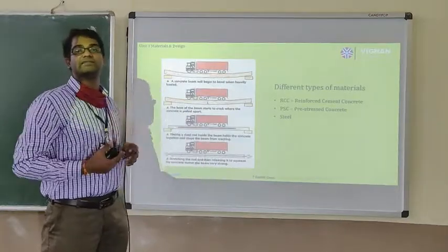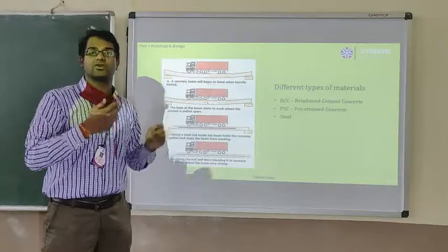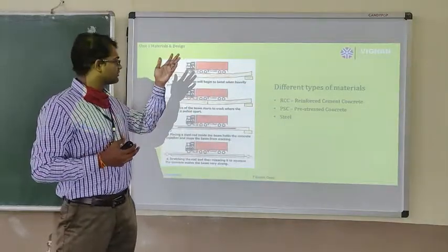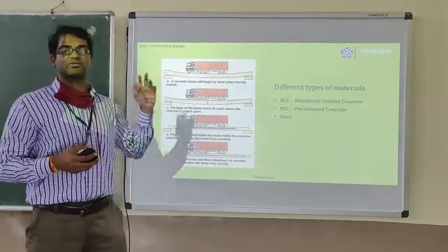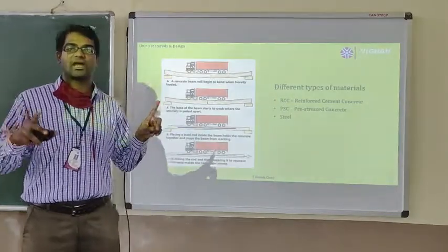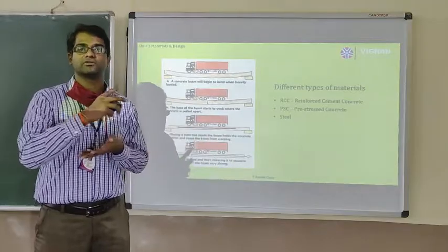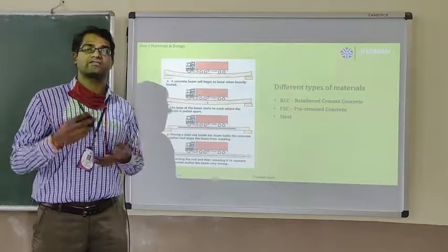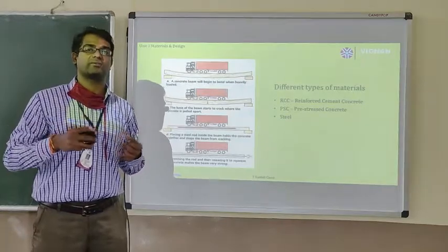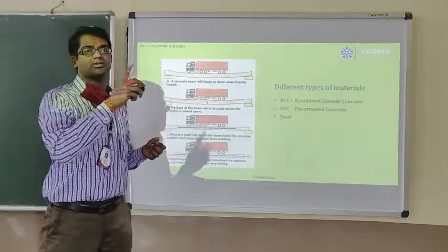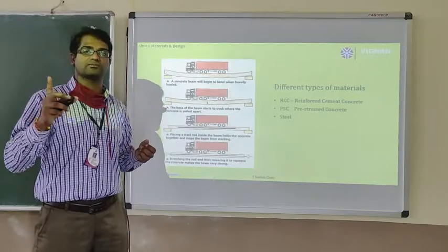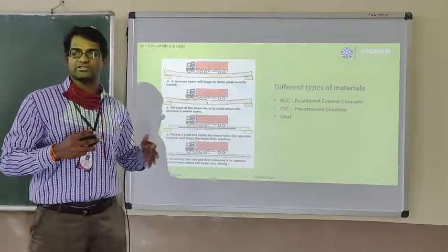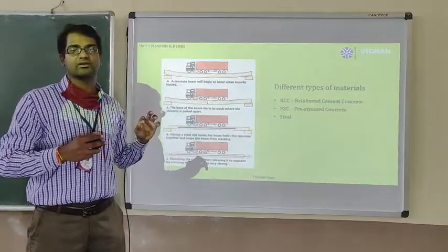The second thing is PSC, which we call pre-stressed concrete structures. I will give a hint of pre-stressed concrete structures. If you take a look at the first picture, you see a bridge and there is a truck which is moving. Now when the truck is moving and if you increase the weight load of the truck, your beam will start to bend. When your beam starts to bend, the bottom portion of your beam will start to crack, which is shown in the second picture.